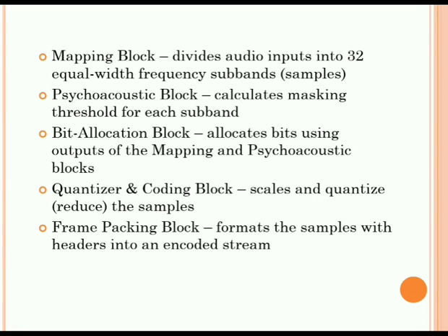The bit allocation block allocates bits using the outputs of the mapping and psychoacoustic blocks. The quantizer and coding block scales and quantizes, that means it reduces the samples. And the frame packing block formats the samples with the headers into the encoded bit stream.